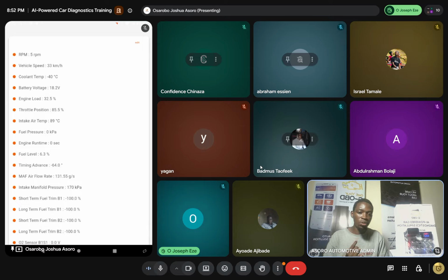So what we have learned today is not just using only the fault code and fault symptom. It is also utilizing the freeze frame. That's the live data snapshot, the live data state, the figures as at the point the fault code came in. Now, if I got a fault code P0 something something and it means misfiring, at that point that the misfiring came up, certain live data will be saved. That's called freeze frame. You now get that and use it.